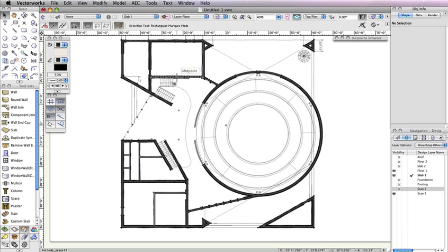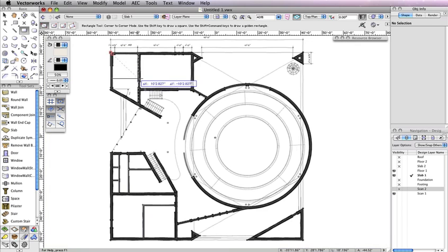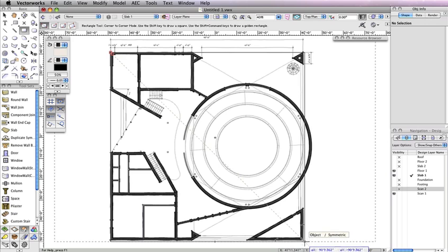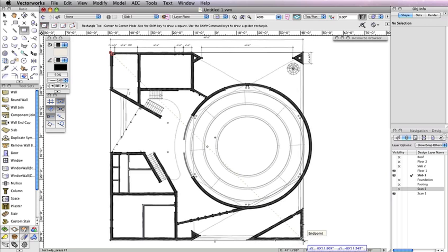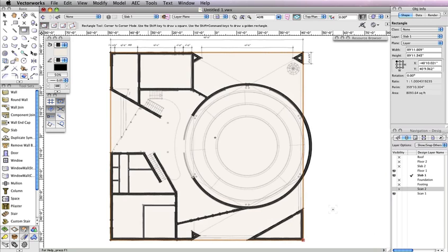Now select the Rectangle tool from the Basic Tool palette. Also choose the first mode, Rectangle mode, in the toolbar. After that, click at the top left corner of the building, where the horizontal and vertical walls meet. Then at the bottom right corner on the opposite end of the building, click once more to create the rectangle. Notice you can still see the walls beneath the rectangle, since we set the opacity for this rectangle to 50%.